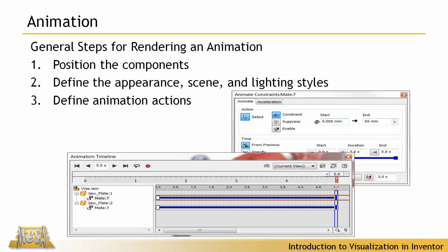We can do positional reps. We can go from position rep 1 to position rep 2. We can change the override or the offset of a constraint. And there's also a component animation, which is a little bit like the presentation environment where you pull things apart. Personally, I like the constraint and the positional reps because that gives me the ability to set those up ahead of time, or at least just change a value.